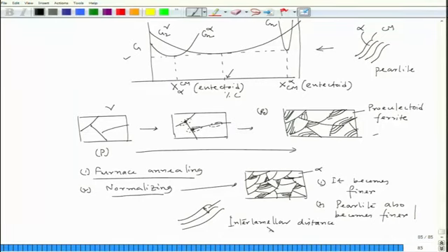We also give a notation for this. Now, if I go for normalizing, that means a higher cooling rate, this interlamellar spacing decreases, that means it becomes finer too. So, if everything becomes finer, that means the amount of grain boundary area is also increasing.